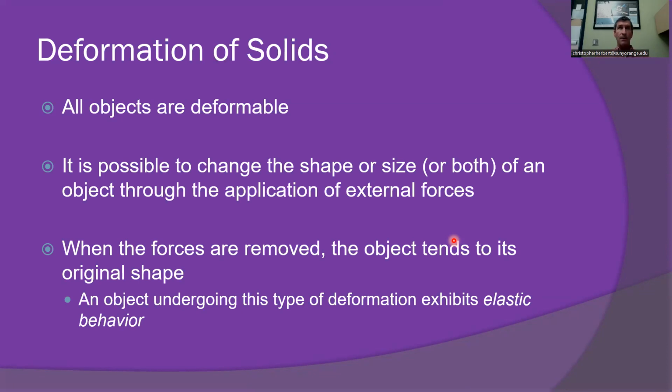We start out by saying, of course, the simplest model for a solid is that all the atoms or molecules in the solid are somehow connected by a bond. It can be a covalent bond, a metallic bond, an ionic bond, or a molecular bond. But essentially, these bonds act like springs, and the amount of deformation that takes place is going to be proportional to the force applied, but also related to how strong these bonds are.